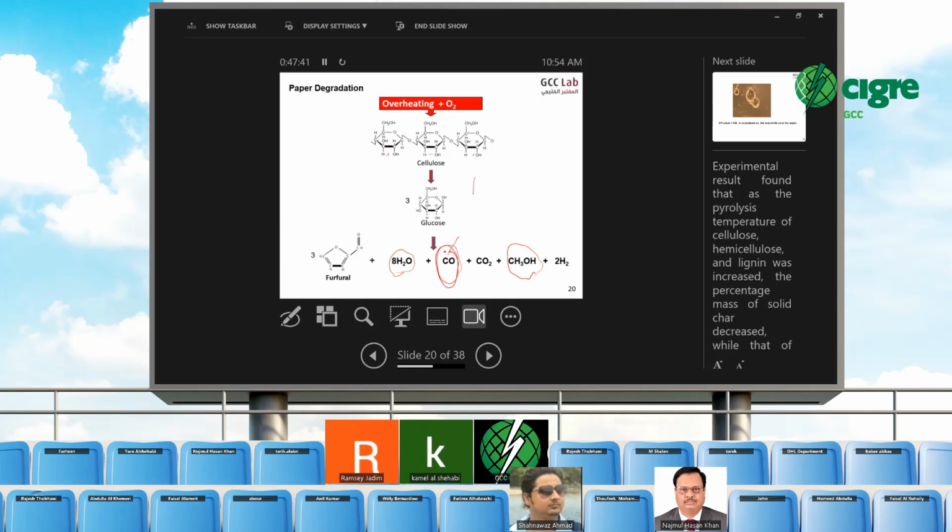DP value here, we take it from the oil, we calculate it related to 2-furfural, 2FAL. So there is an equation between them. There are international methods, many equations, but we use one equation that we think is okay.